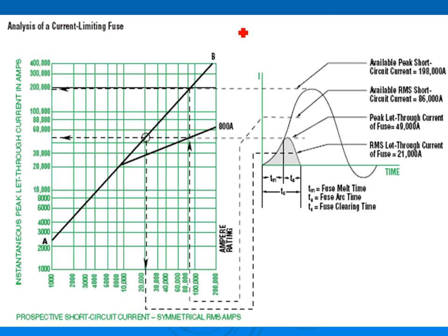Look, really interesting. So I want to draw the line right here. Here's my disconnect. Here's my current limiting fuse. And here's my machine, my VFD or soft start controller. And here's my machine that I'm feeding, right? So I need to protect this equipment, guys.